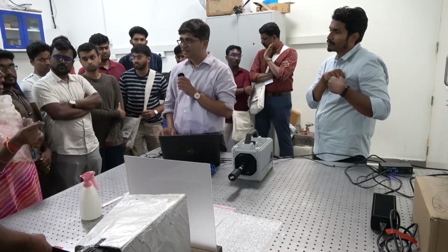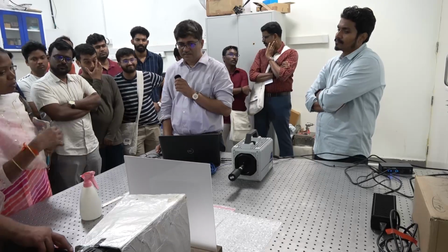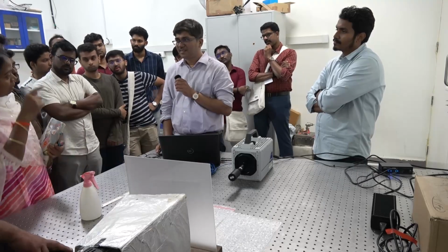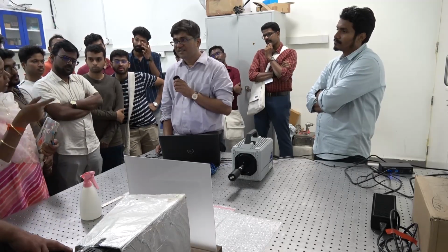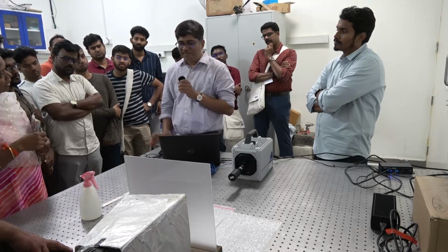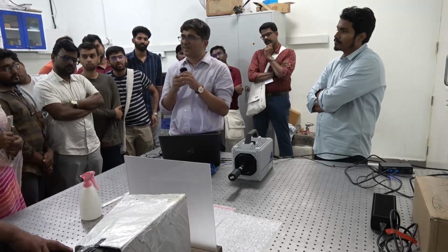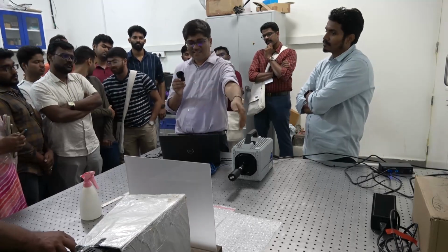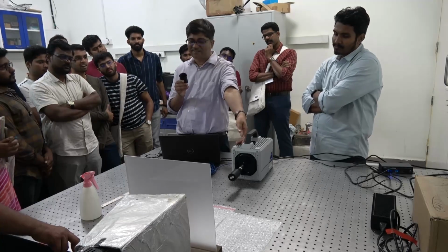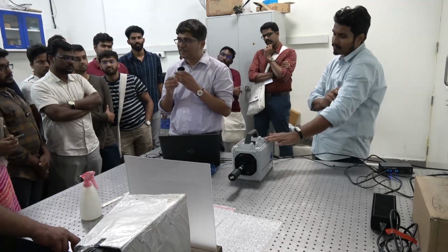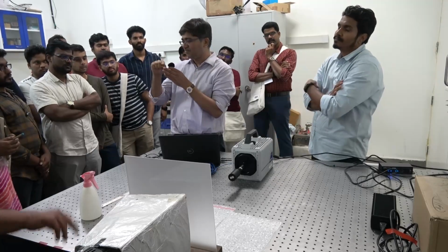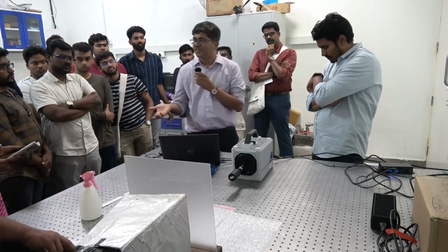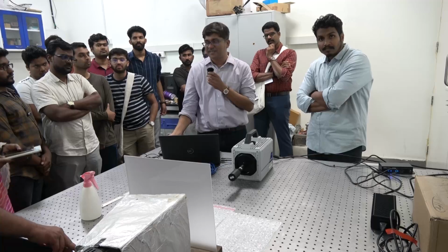Can I measure the contact angle between the droplet and this surface, suppose this needle is made? Yes, definitely. You have a surface, right? That's how contact angle measurement works. This is the same principle. They will have a light and a camera. You need not have a high speed camera, a normal camera will do. Then you can just fit and measure the contact angle. From that contact angle measurement you get surface tension. Surface tension measurements, they do that.